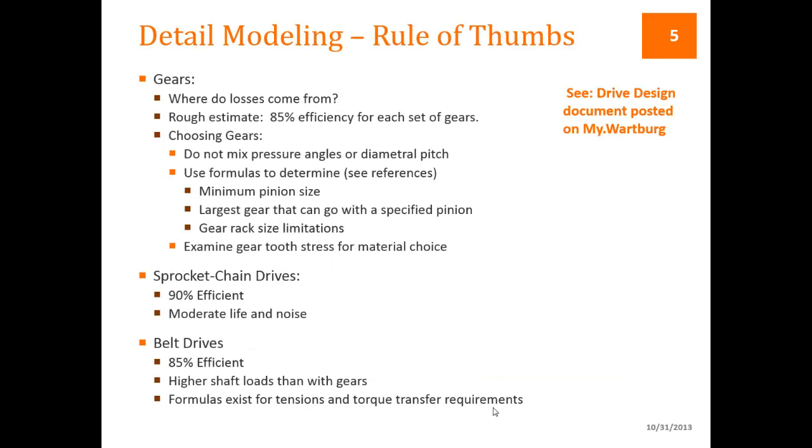That will allow you to examine gear tooth stress, which is important to make sure that your gear actually can withstand the forces that your design is applying to it. Especially important to give you an indication of material choice. So do you need hardened steel? Can you get away with plastic?